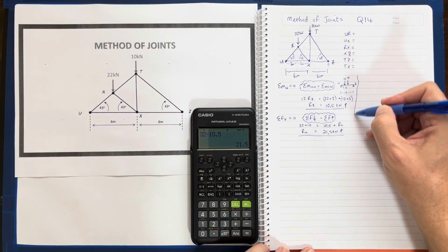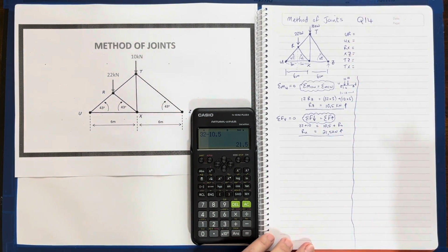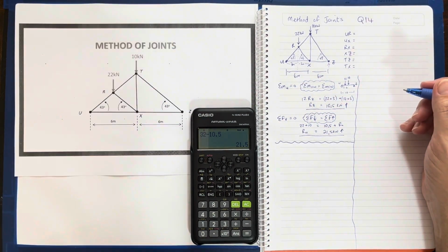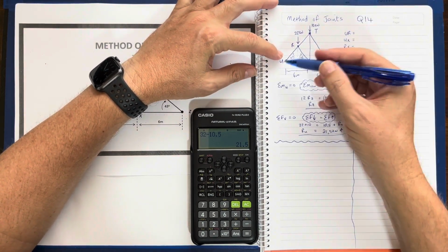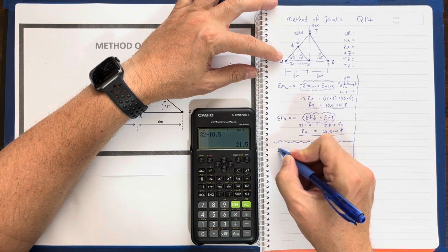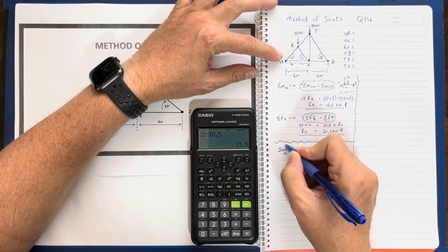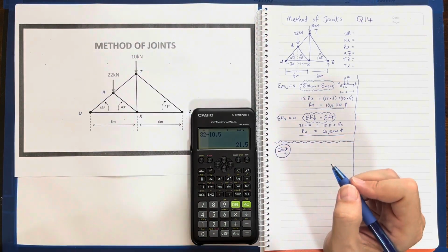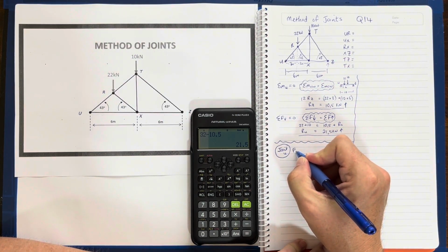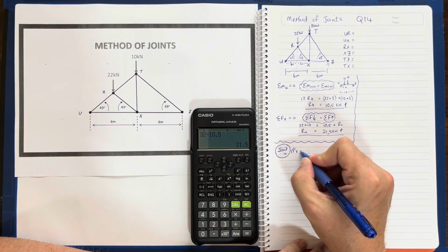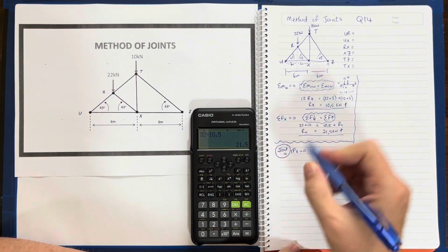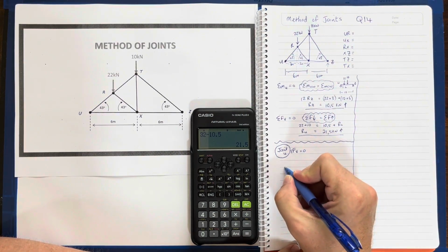Okay, so I'm going to draw a bit of a thing down the side here, a little barrier, and I'm going to start at the most obvious place. I'm going to start at point U. Start in the left hand corner, and the first thing I'm going to do is go to joint U. Tell the person who is going to be marking your paper or your sum, I'm starting at point U, and I'm going to say the forces vertical should say sum of forces equal 0. I know my sum of my forces down will equal my forces up, and what I do is I look at that joint and I draw that joint.